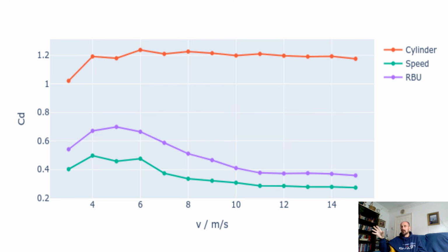It's probably around your best glide speed for a lot of gliders, but you will often be flying quite a bit faster than that. But because we can see that the coefficient of drag is flatlining at those speeds, it's probably a fair bet that it's staying fairly flat out to those higher speeds as well. So we can treat the coefficient of drag as constant at those higher speeds, which is very useful for calculations and for prediction of performance.